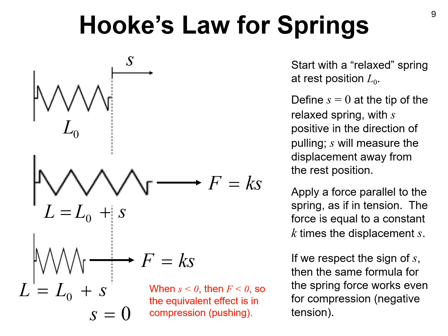And what you've already learned in the vector resultant module is that if I have a negative value pulling to the right, that's the same as a positive value pushing to the left. So Hooke's law does work for both tension and compression with one law. We don't need a separate law for the tension and compression cases. This is something you want to get used to, because again, I acknowledge it looks a little bit different, but this is the way I recommend thinking about it.